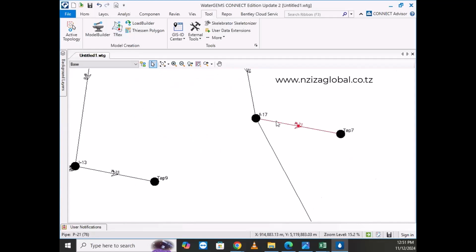So I want one of our friends to tell us the criteria which can guide us to size those pipes, especially velocity. I think it is the one that you need first. Which velocity can we take? You can take 0.5 to not above 1.5. We keep that? Yes. Okay, let's keep that.